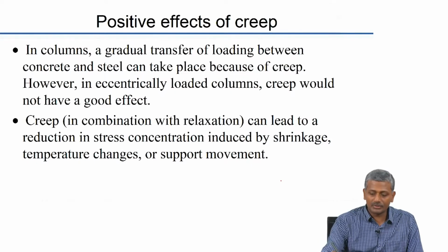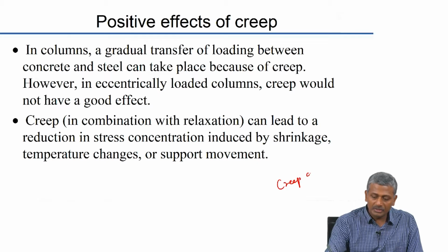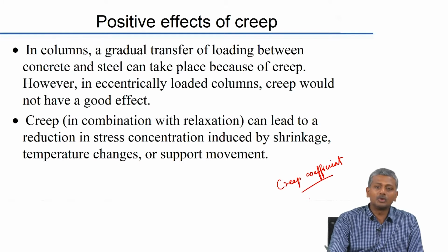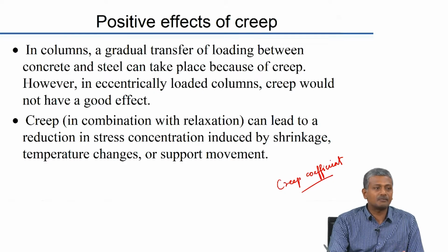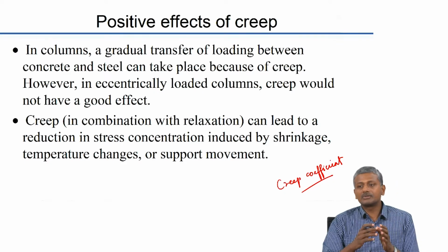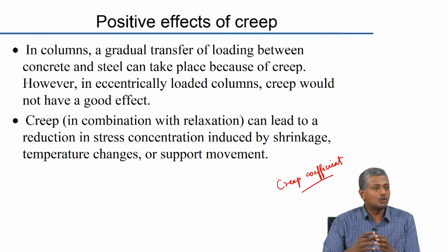Currently, how do we actually incorporate creep in the design process? The definition of what is called a creep coefficient. So, a creep coefficient is basically a ratio of the permanent or built up strain divided by the original elastic strain, okay. And based on the concrete mix designs that were used in the past, there is a statistically valid value of the creep coefficient that has been incorporated in the design process, okay.